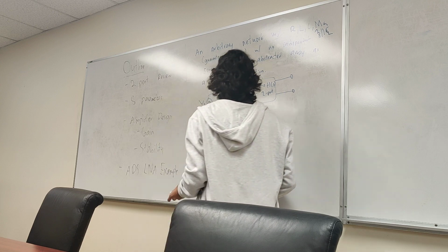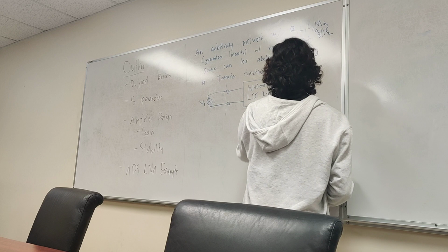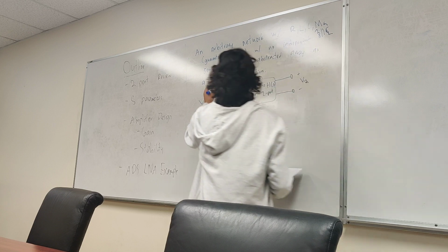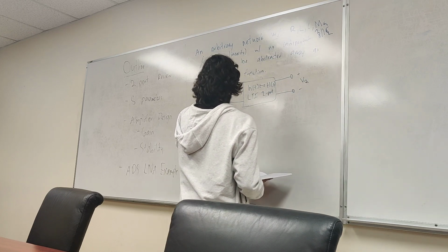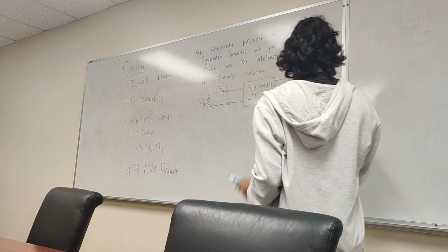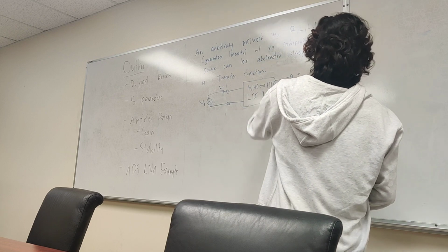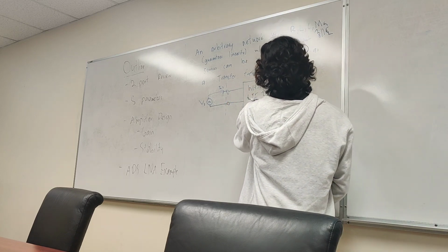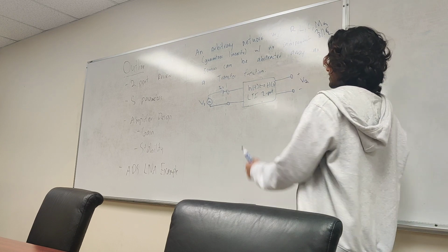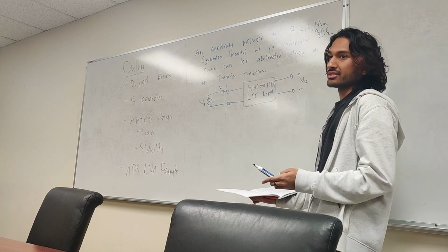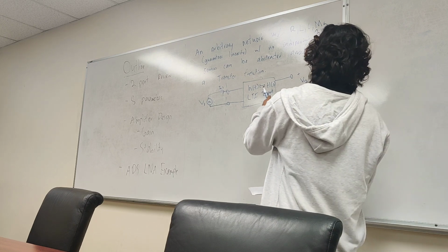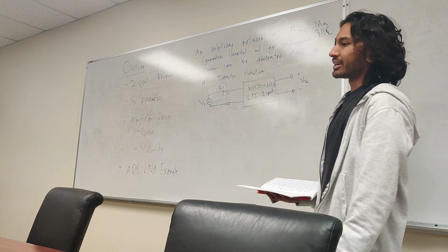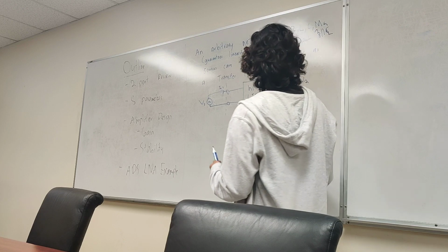We can just say that V1 is being sent into this network, and we can measure a corresponding V2. Kind of straightforward. We have a closed loop here, so we're going to have some current here, and there's no current here. This makes sense intuitively. Now, I said that we can model this as a transfer function. When we talk about transfer functions, we have an input, multiplied by a transfer function, you get your output. If this is like a voltage divider, then we can get a transfer function from it. So how could we take this 2-port, with these 4 terminals, and represent this in some mathematical notation that allows us to do circuit manipulation?